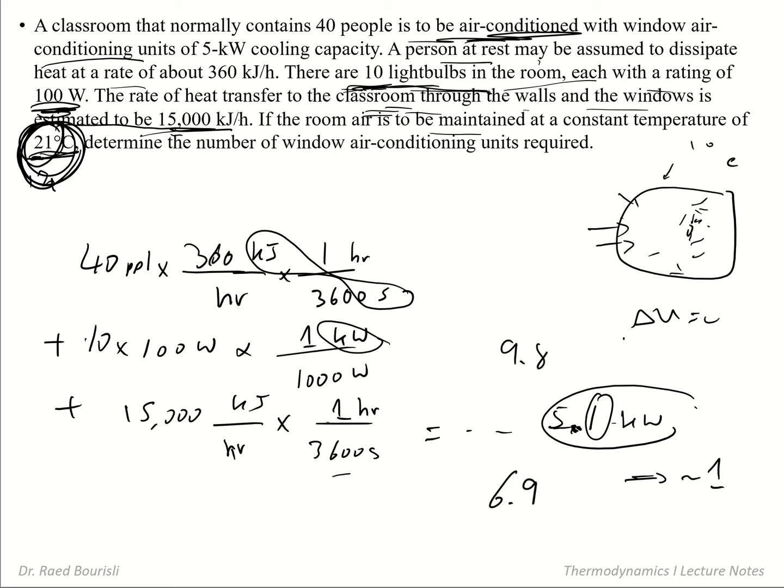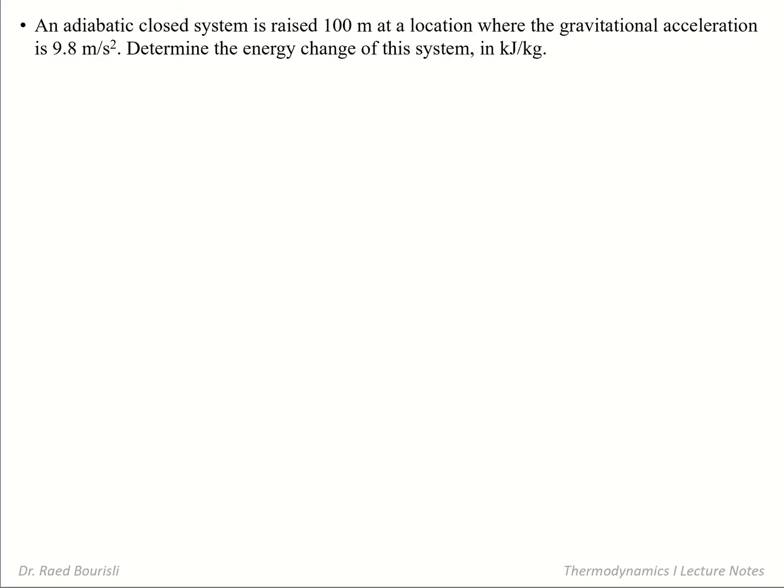If it's 9.8 kilowatts, then I need 2 of them. If it's 10.3, I'll get 2 again. The heat addition is in kilowatts, and one of them will remove 5, so I'll just suffer for 1 hour. It's safe for 1 hour or half an hour where everything is at maximum power. So this is how we do it. This is from the book.